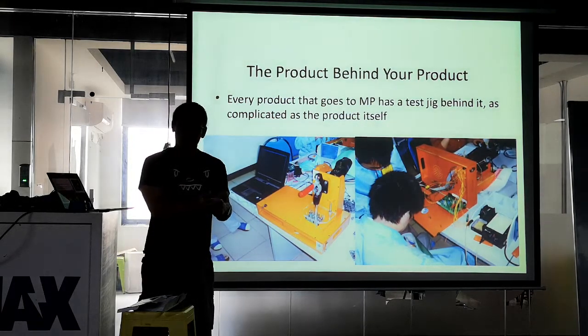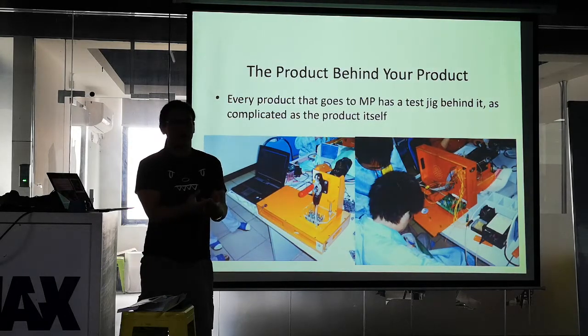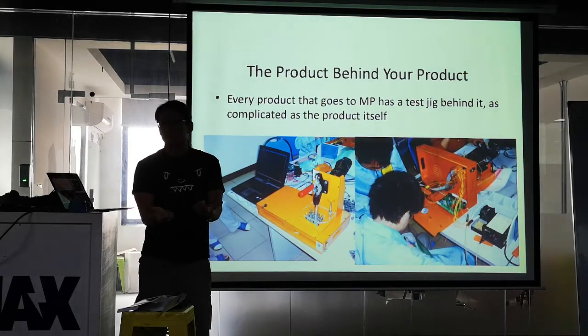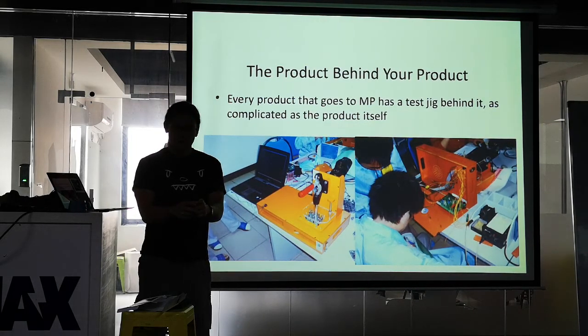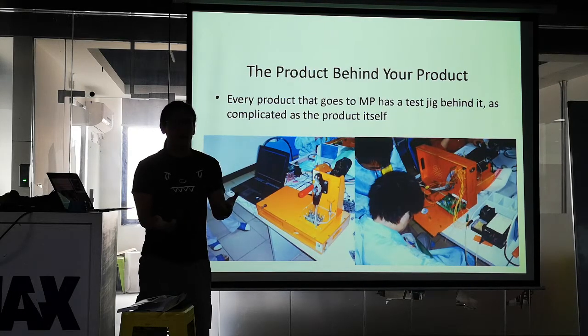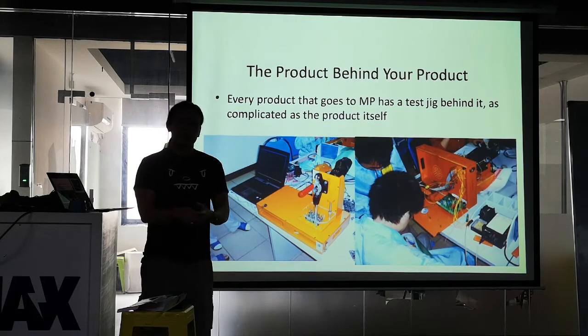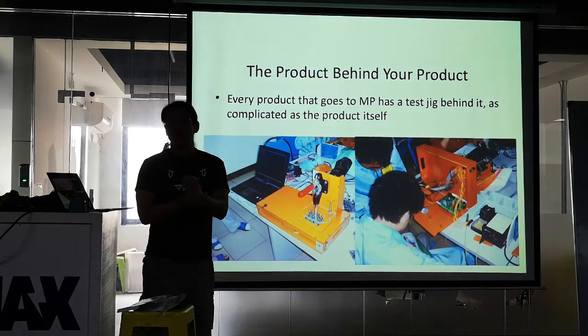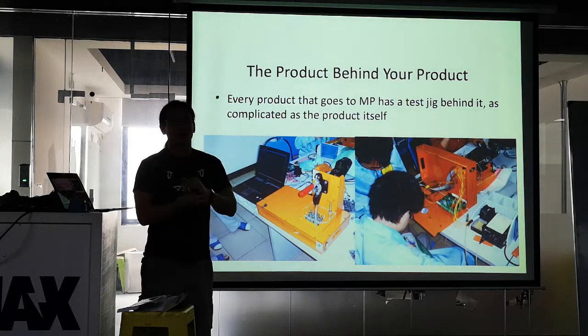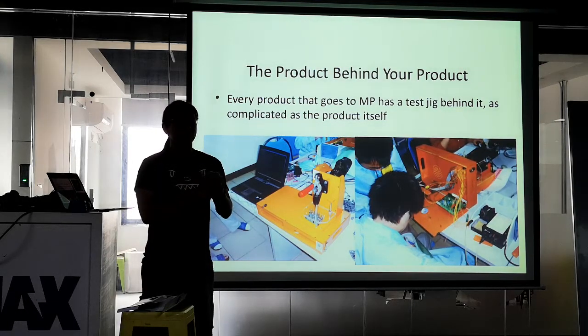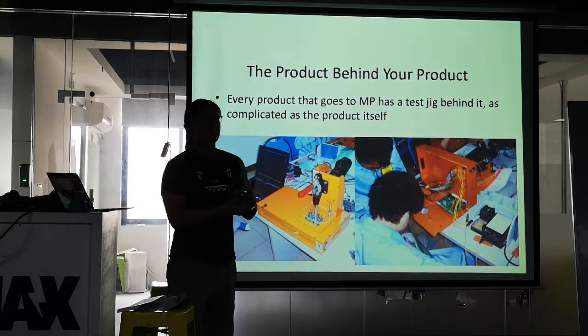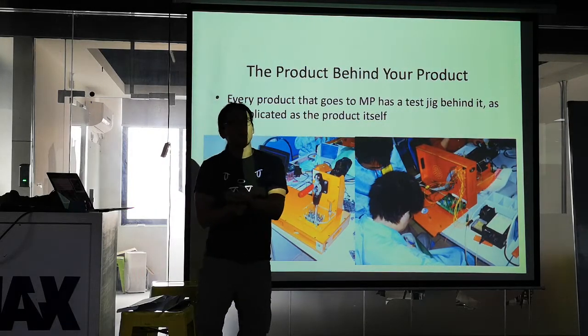You're worried about the firmware on it and the Wi-Fi and all that sort of stuff. How do you test that it works, right? Think about everything that has to go into testing that. You have to be able to put the firmware on in the first place, so you need a JTAG interface. You have to test the Wi-Fi, so now you need a base station. You have to test the Wi-Fi performance, so now you're talking about RF measurement. You have to test that your sensors are working well. If you have a pulse oximeter or something like this, you have to have a human model of something in there to confirm the pulse oximeter is working. This is actually a really complicated issue to work through.